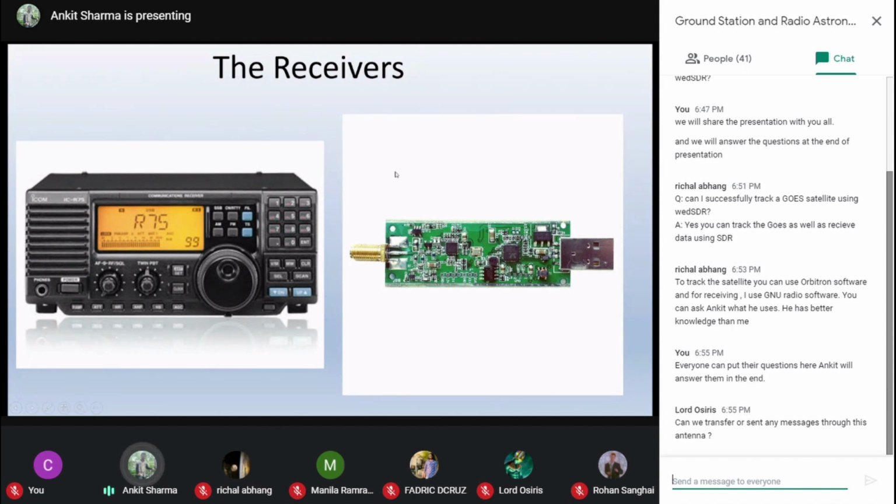So it's quite a good gadget which has been in the market, and definitely I use RTL SDR. Basically, you can use any type of SDR depending upon the frequency range. So each SDR has their separate frequency ranges. RTL SDR works good for weather satellites, UHF, VHF, and as well as geostationary satellites. Also, it works good in the L band. Basically, above L band, it doesn't have any reception as such. But yeah, so this is basically your SDRs.